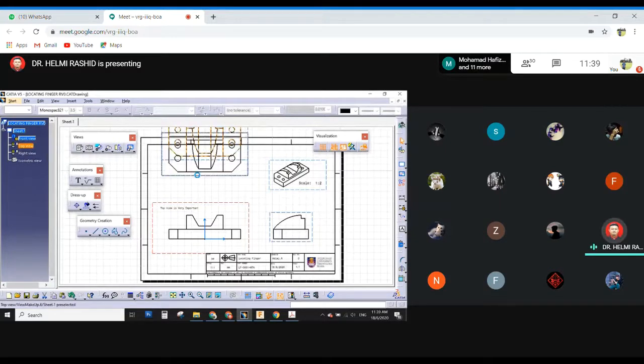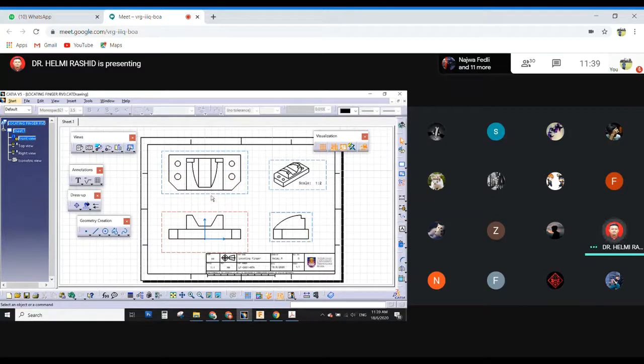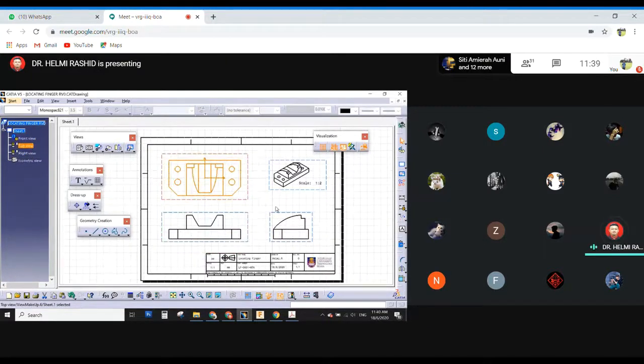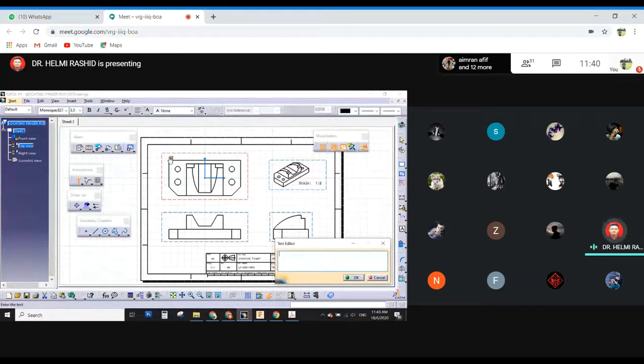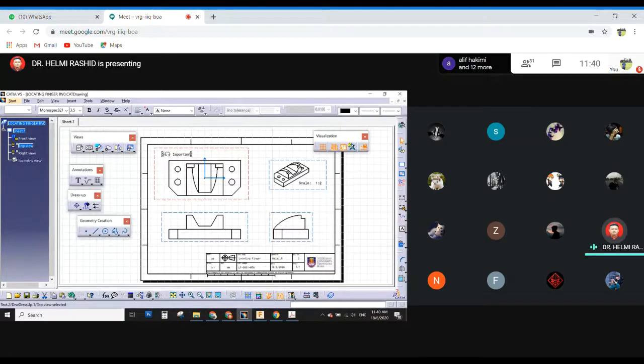Right? So this is where, if you want to put in some annotations in the respective projection view, you need to double click on your specific view. So let's say the top view again here, right? So when I put an annotation in it, I put 'is very important', you can see I'm putting it in the top view territory.